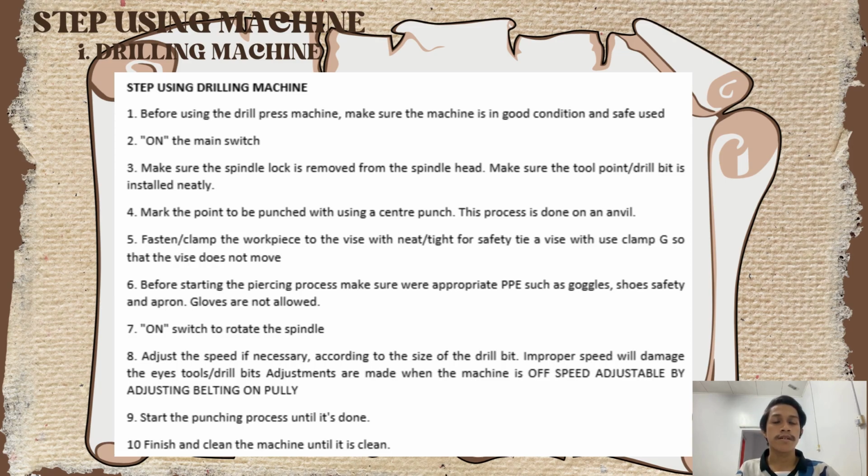Sixth, wear appropriate safety clothes. Seventh, turn on the switch to rotate the spindle. Eighth, adjust the speed if necessary. Ninth, start the drilling process until done. Tenth, finish and clean the machine.